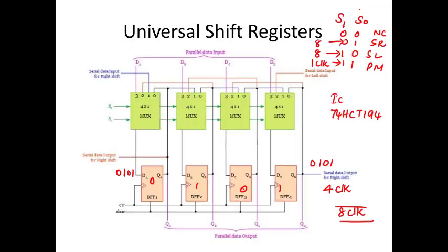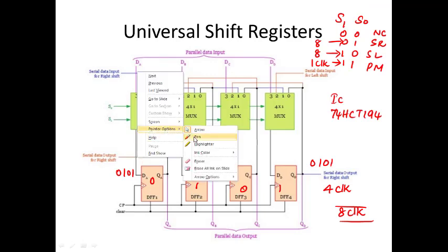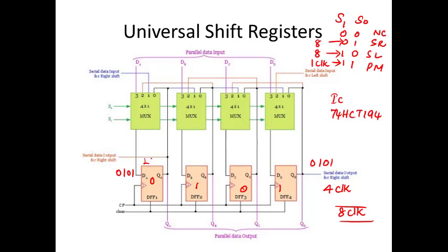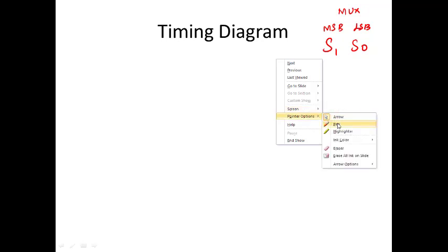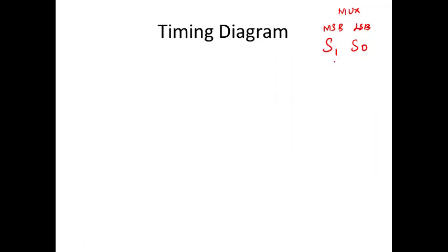And already I said for the shift register, this is going to be your LSB, and this is going to be your most significant bit. That is what you usually think, this is LSB and this is MSB usually. You keep that in mind. So now, I said we need to define the operation. How am I going to define my operation is, first let me take the shift right operation, where 0 1 is the shift right operation.